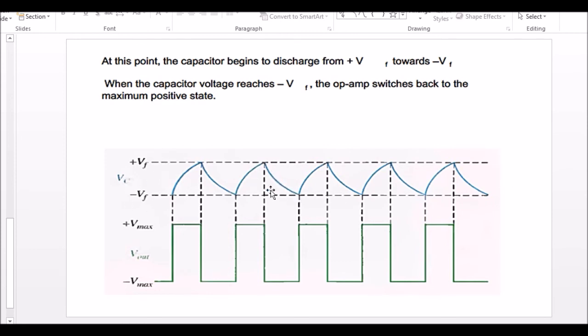So this is your input terminal waveform. When you apply it to a differentiator, let's say it's a triangular wave, and you apply d by dt to it, what will happen? A constant amplitude. So this is how you're generating your square waveform oscillator. These are the three sets of relaxation oscillators which you would be covering in your lab. So this is all for your theory part.